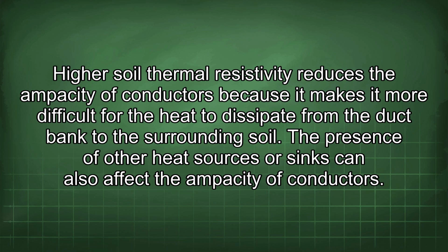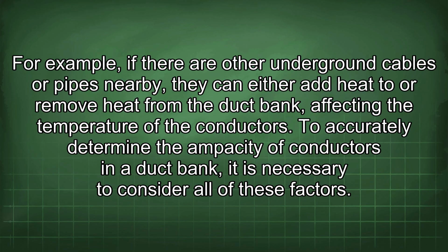The presence of other heat sources or sinks can also affect the ampacity of conductors. For example, if there are other underground cables or pipes nearby, they can either add heat or remove heat from the duct bank, affecting the temperature of the conductors. To accurately determine the ampacity of conductors in a duct bank, it is necessary to consider all of these factors.